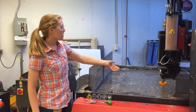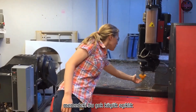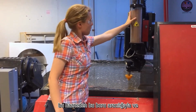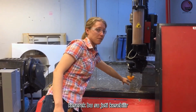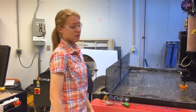The water jet cutter uses a stream of highly pressurized water and abrasive garnet, which gets blasted out through this very small opening in the nozzle. The garnet that I mentioned is pulled from this hopper through this tube and is mixed in with the water to help with cutting. This water jet can cut through almost any material, including metal, plastic, you name it.